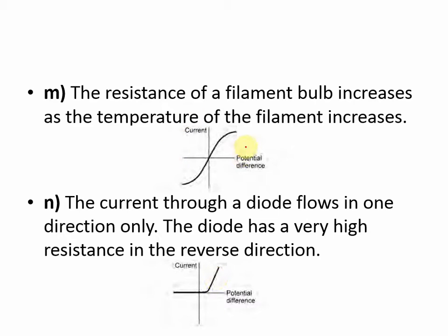You might need to play this part of the video back a couple of times to make sure you understand it. So, what happens here is as the voltage increases, the current increases. As the current increases, the temperature increases. As the temperature increases, the resistance increases. So it means the current can't increase as much, only a little increase. That's why it levels off. That's why you have that shape graph that you do over here, the fact that it curves like so, a curved shape like so.